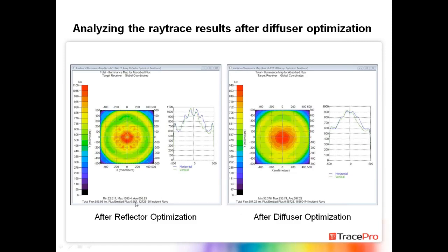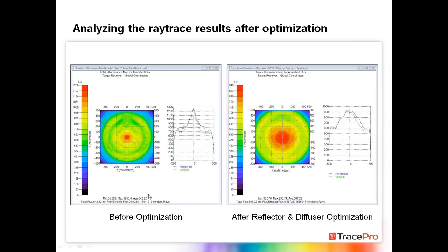And after the optimization is finished, it's saying here that the solution highlighted in red is the third property. In this case, it was Moltec_3. So I applied that property to the model and reran the ray trace. A couple things to notice here. Those little spikes are pretty much minimized there. We have a much smoother profile across the center. We don't see all that structure. So adding the diffuser has improved the results.